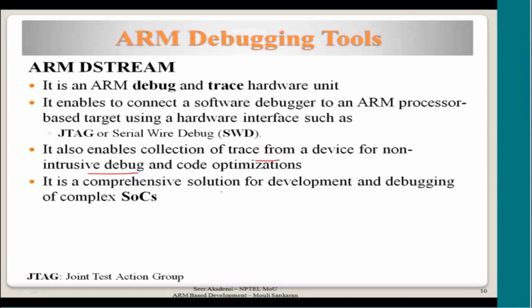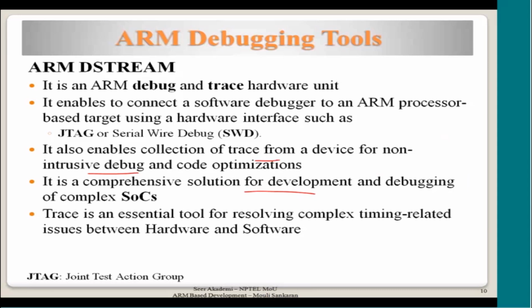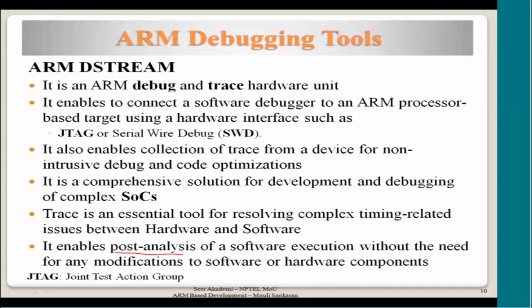So it is a comprehensive solution for development and debugging of a complex SoC. That's the summary. Trace is an essential tool for resolving complex timing related issues. As I told you, whether any particular module is taking more time, that also can be resolved, or any particular interrupt is coming and some event is happening at a particular time when the system is crashing. This kind of very specific event can also be traced and then analyzed to find out the cause of a problem.